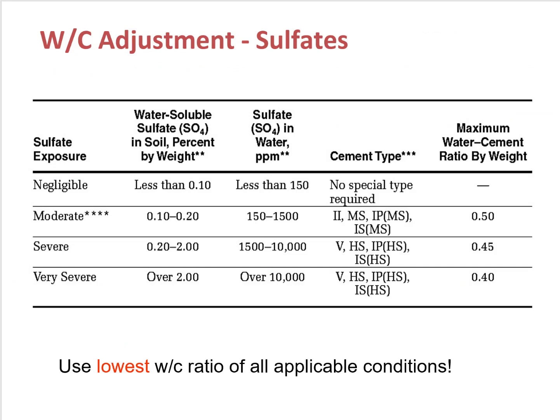And in this figure, you can find the maximum water to cement ratio for the concrete exposed to sulfates in soil or water. And depending on how severe the sulfate exposure is, you can find the maximum water to cement ratio values in this table.